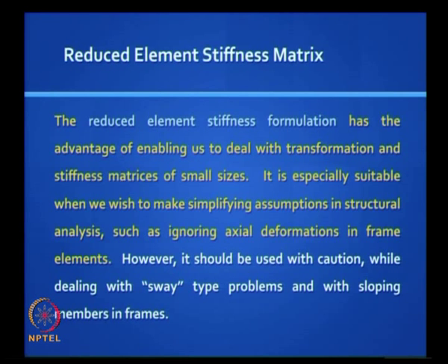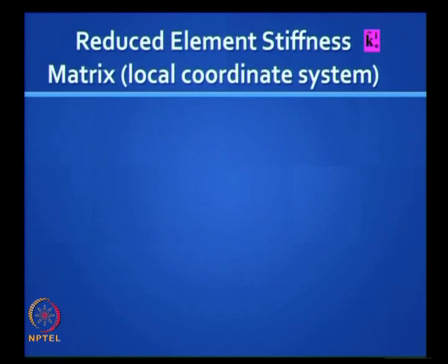However, it should be used with caution when dealing with sway type problems and those treacherous problems we have seen where the columns are sloping. There you have to use extra brain work, not worth it, might as well use a software way of doing it, okay. So you must use the right instrument for the right occasion. You do not use an elephant to drive a small nail, but we end up doing that.